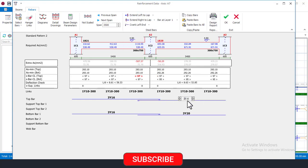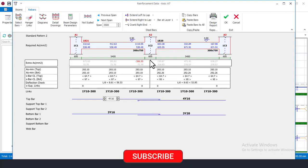Okay, and I'll now come here right now. It is still failing at the top here. You can see that this extra area of steel here is still failing, as you can see. So I'll come here and make it to be 4Y16 and come here again to be 4Y16. At that, it is still failing right now. I can choose to use Y20 and then Y20 here and all that. But if I don't want to do that, I can still come back and then reduce to Y16 and Y16 here.